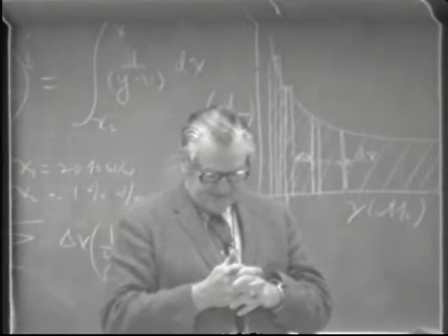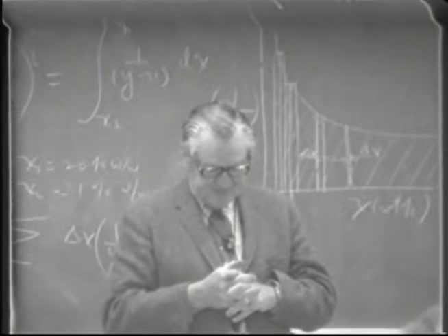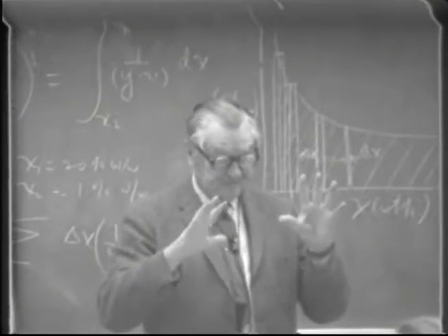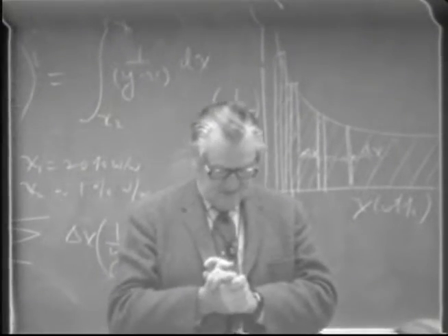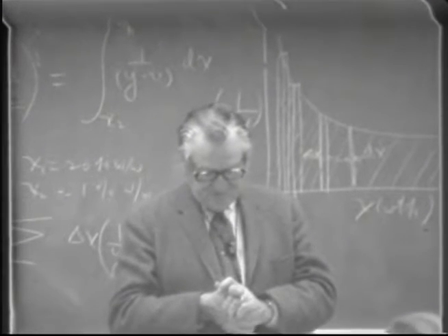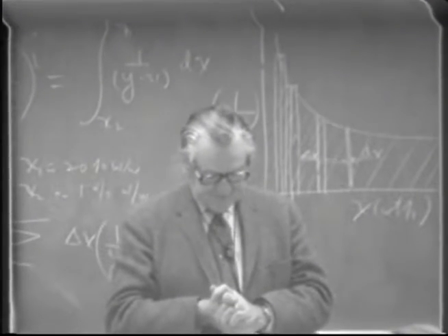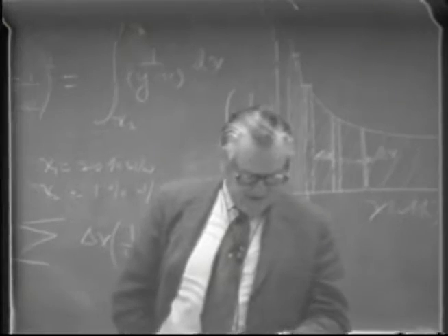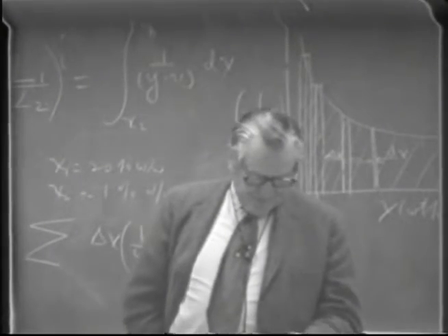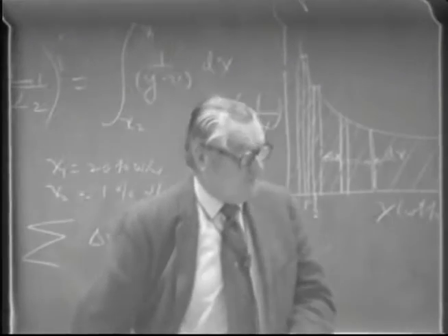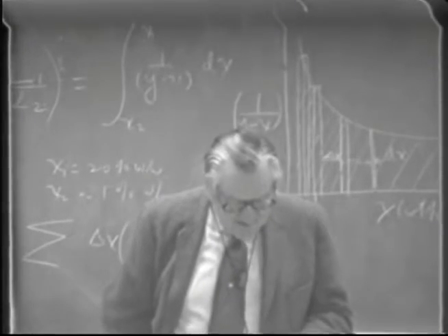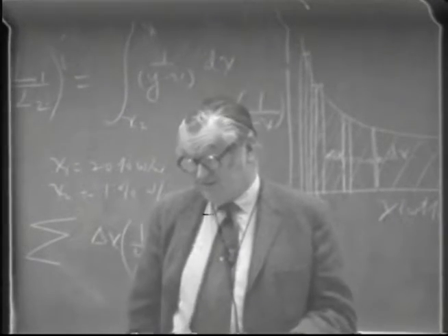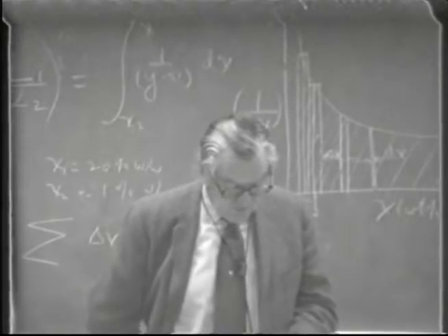And so if you want to look at the curve which says the percent of the isoamyl alcohol removed in the oil phase, that means the percent of the initial amount fed to the decanter. You see in figures 4 and 5 there that it goes through a maximum. In the case of figure 4, for mixture A, at about 2.5 parts of water per part of low oils, or fusel oil fraction. In the next case, it is only about 1 to 1 water ratio.